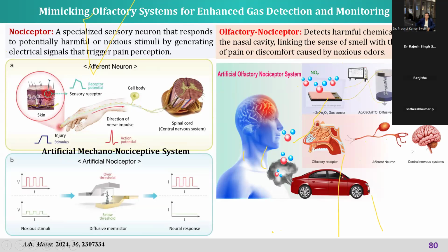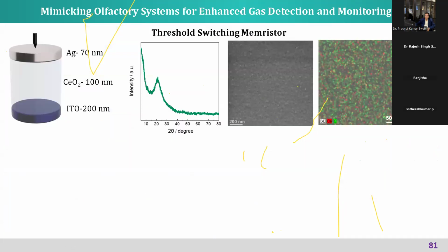A resistive switching device is nothing but a device having multiple resistance states. In this case we have two resistance states, and we can take the device to a low resistance state or a high resistance state by applying a bias. Now by connecting this in series, what is happening? This is what is of interest.